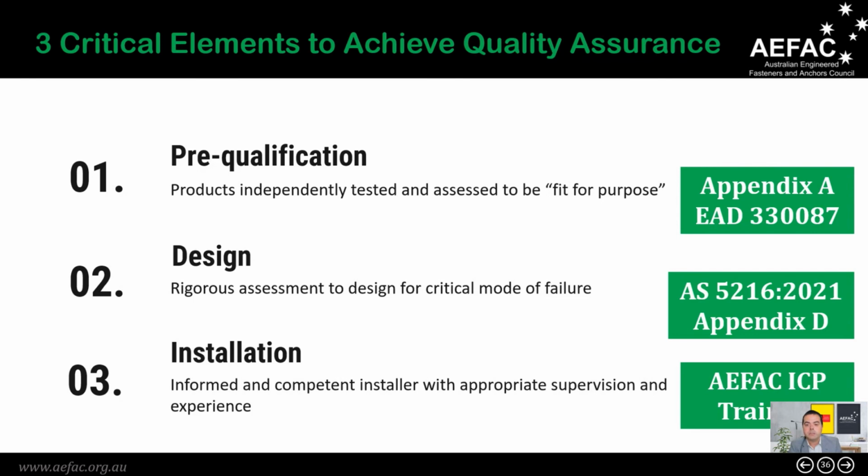The second one is the design. The design of post-installed reinforcing bar is now covered in AS 5216-2016 in Appendix D. So the concrete cone capacity does not apply, and we use a rebar model to design a post-installed rebar connection. And finally, the installation is very important.